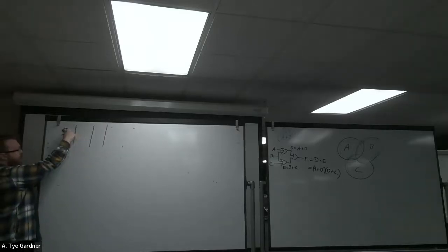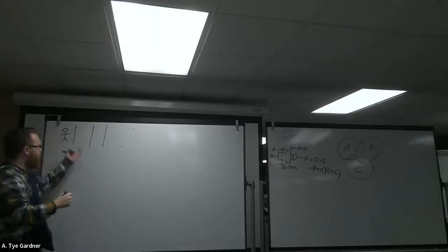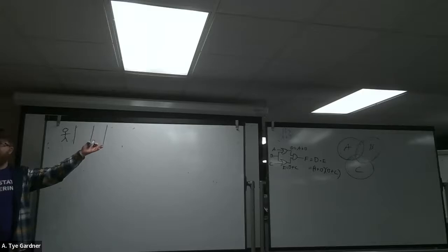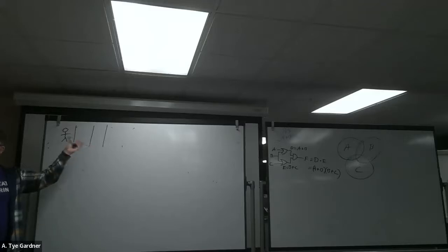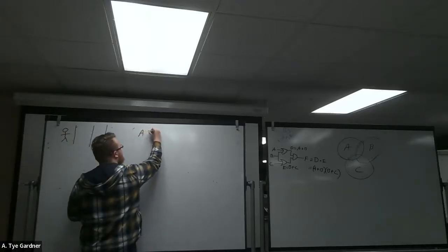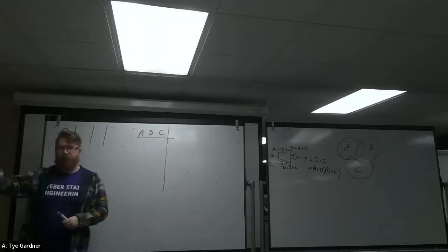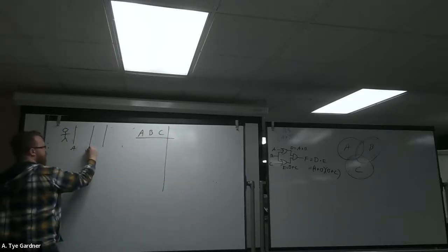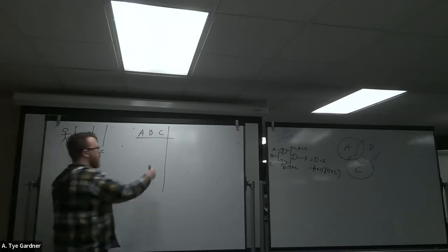You open this door, you step in, the door closes. That step, right, you walk through, it's the airlock. You ever watch sci-fi? But this is just a 2-stage airlock. And we want a circuit that says, if 2 of these doors open, lock the 3rd door. No matter what happens, that 3rd door cannot open if the other 2 are open. So my signals A, B, and C are going to be true if doors A, B, or C are open. That's all they're saying is this door is open. So I write up the truth table.